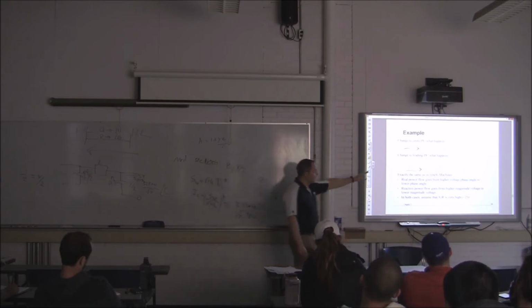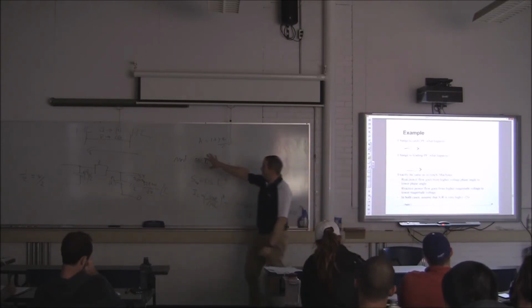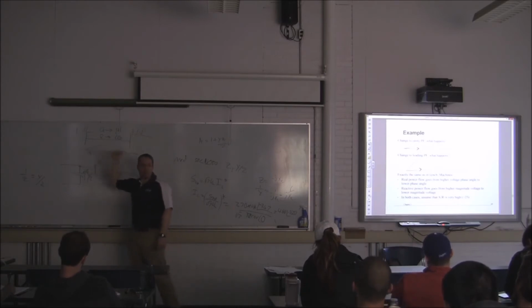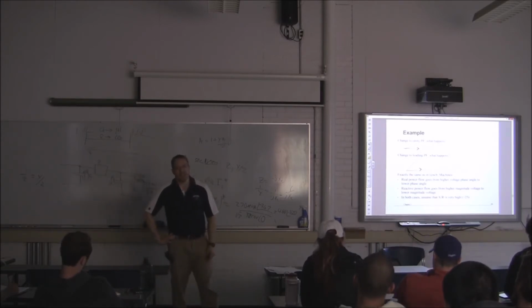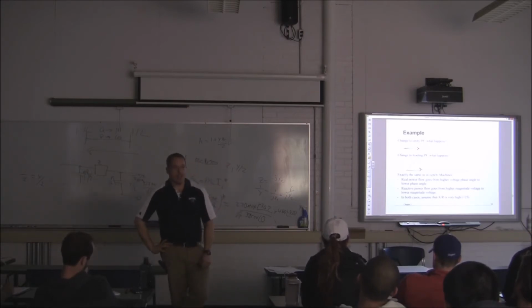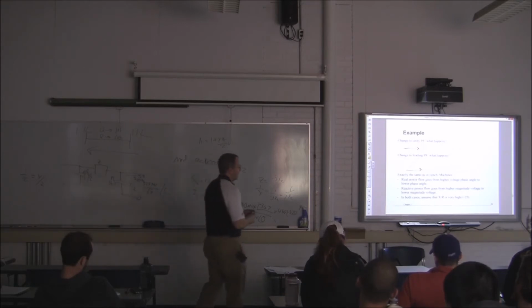And power is still flowing from the sending end to the receiving end, because just because I have a leading power factor here doesn't mean I've added a generator on this side. So power still has to flow in this direction, from sending end to receiving end. Does that figure still validate us? Does it seem like it's accurate? The angle associated with Vs is more positive than the angle associated with Vr. So therefore, it's the case.